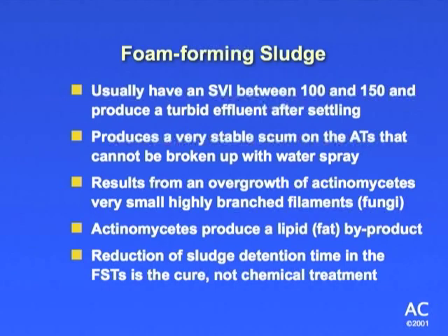I've actually started up plants by using seed sludge from another plant. Sometimes it works, sometimes it doesn't, where I've had trouble. In general, if I've got a new plant to start up, if I can just do it with the mixed liquor, forming the mixed liquor from the influent coming in, and let it gradually build on what's normally being fed to it from the community, I'd rather go that route, because that's what it's normally going to be fed off of anyways. But I have started a plant one time where we brought in sludge from an adjacent plant, and it was more headache than it was worth. We actually inherited their foam problem. But then I've done another plant too, where it was right nearby, and very similar influent characteristics. We trucked the sludge over, no problem starting it up.